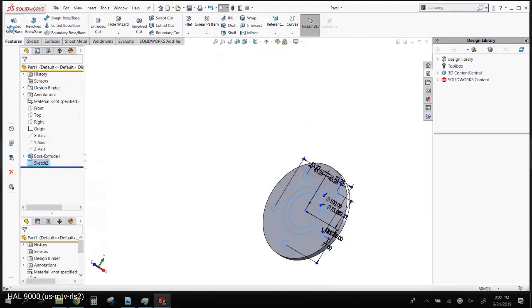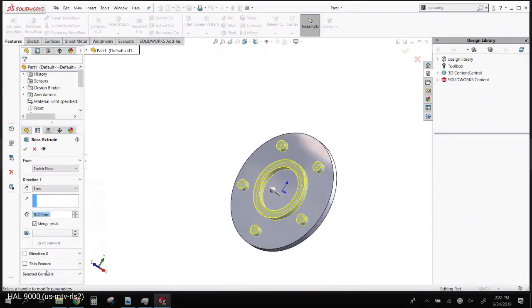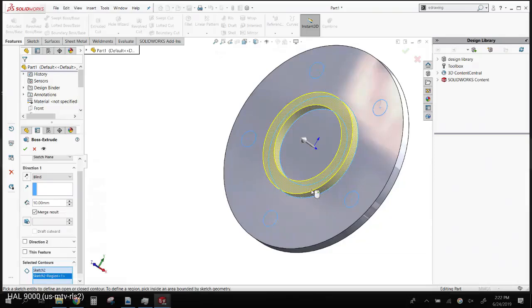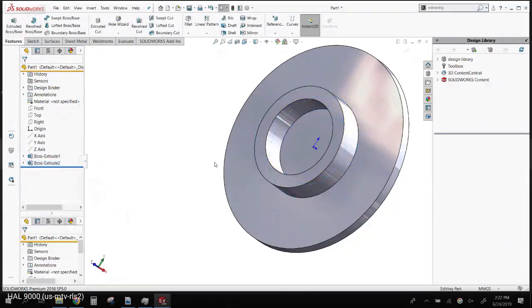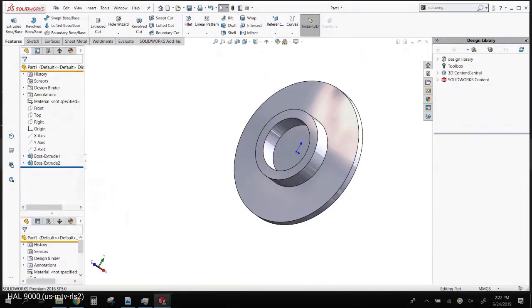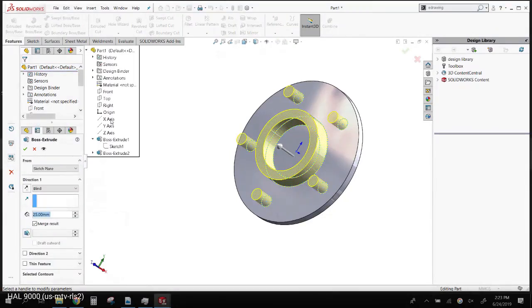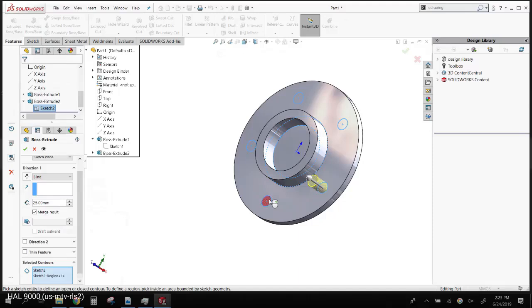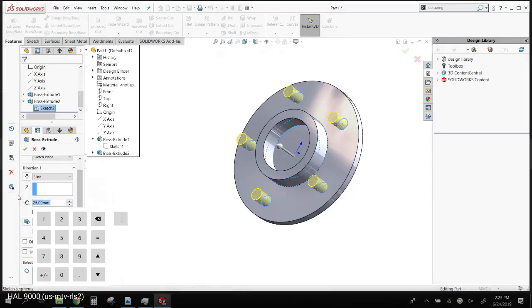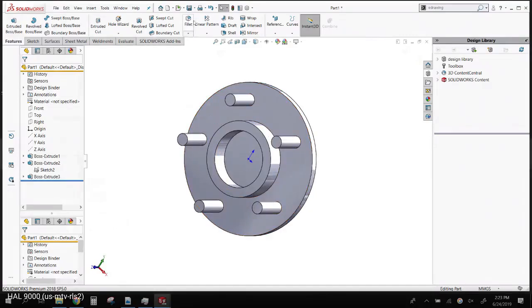So I'm going to do a couple of extrusions here. By default, SolidWorks wants to extrude the entire sketch. I can change that and say, no, let's just extrude that section right there, that much. I wasn't finished with the sketch. It's okay. Select on it again, hit extrude again. I'm extruding with the same geometry. I just need to tell it what I want to extrude, which is these mounting bosses. There we go. Okay.